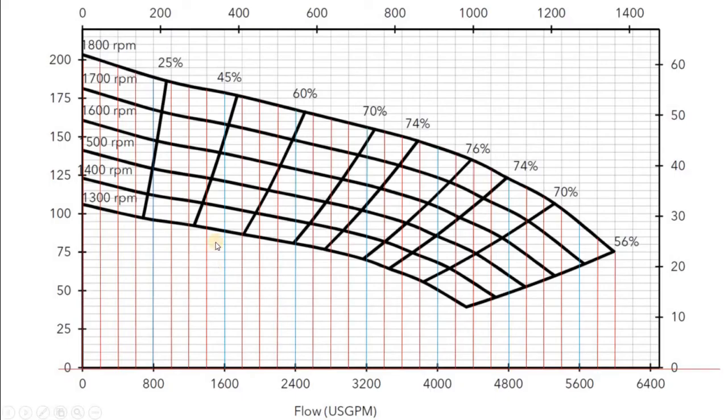When you receive the 3 pumps curves from the vendor, you would need to transfer this graph into values to your Excel sheet. So what I do normally is, instead of measuring it with a ruler, I use something like PowerPoint or AutoCAD or something, draw some lines between the reference and the curve and just measure those lines and put them into an Excel sheet. In this case, I have gallon per minute on this curve X and I have foot in this head. I can take it and convert them into meter cube per hour and meter as heads. So now we will go into the Excel sheet to see where we are and how we will do it.